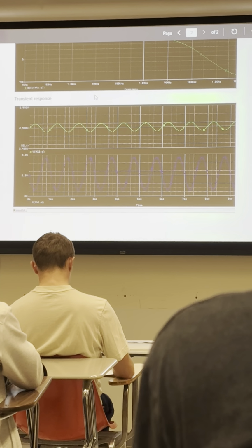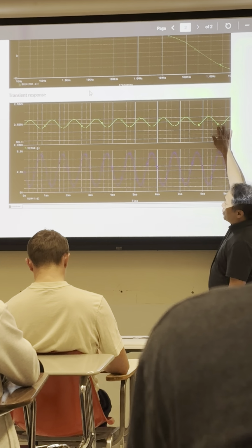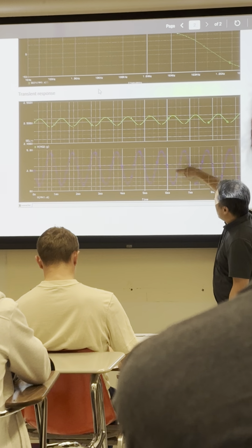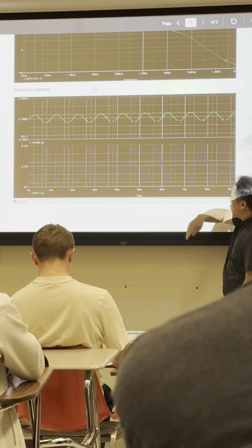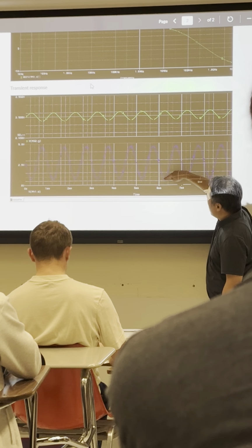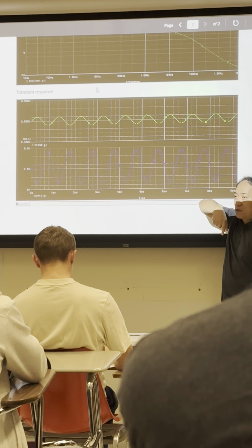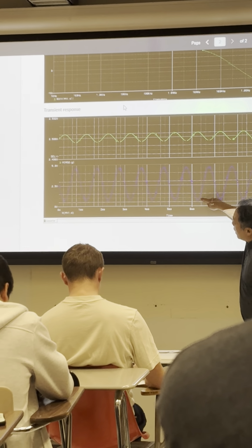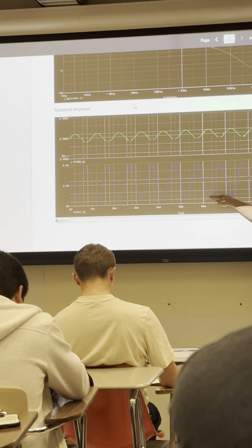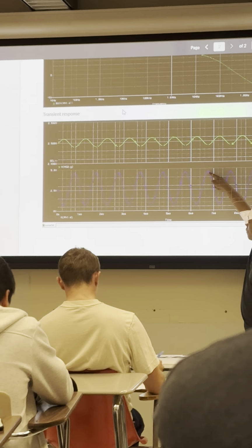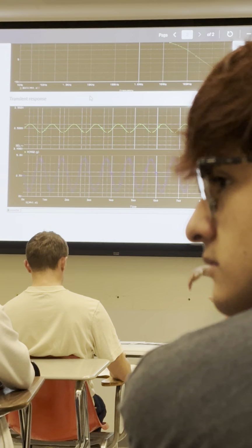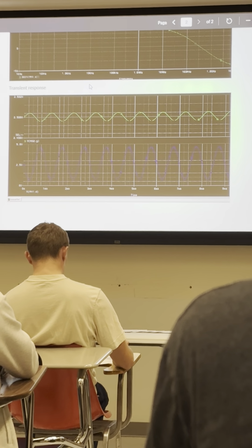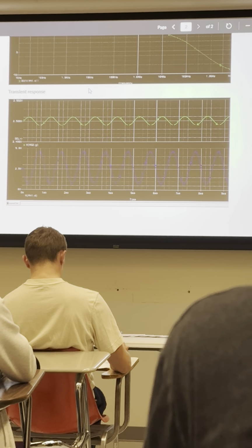And this is just to show you the transient response. This is my input signal, and this is my output signal. I just want to see nice sine wave signals from your output. You can also find your minimum and maximum output voltage from this one, so you can find the output range. In this case, your minimum looks like 1 point something. Your maximum is close to 5 volts. I'm pretty sure the output swing is more than 4 volts. So these are the simulation results you need to show me in your report.